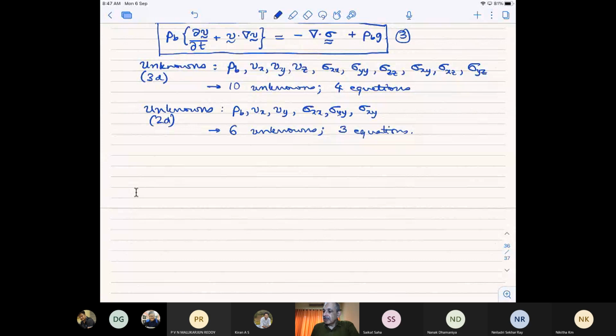So what does this mean, and what does this imply? What this implies is that you need what are known as constitutive equations. And these tell you what is the material behavior. For a Newtonian fluid, we know that simple equation of tau, or you can write the stress in terms of the rate of deformation tensor, and that gives us enough additional equations to solve the problem.